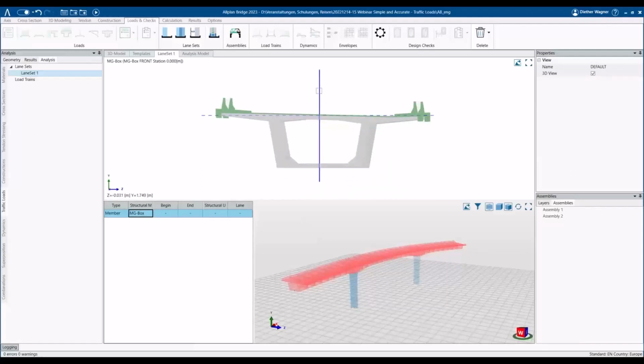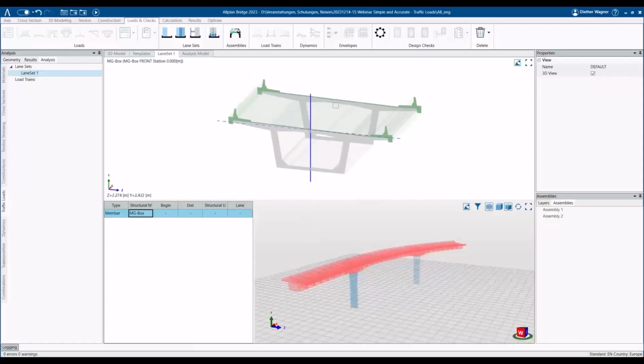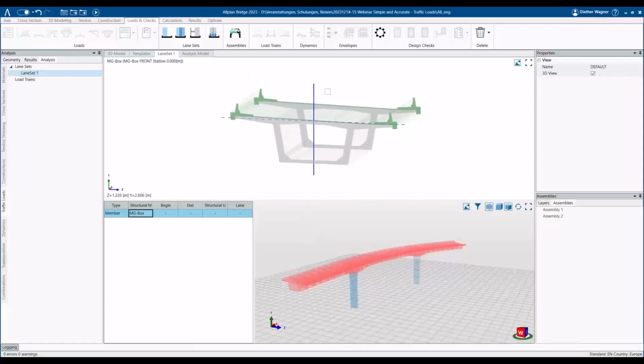So if I now would start to define a lane, it would refer to that line. We can also shift this afterwards. You will also see this in a minute when we then copy it. But I will do it right now at the beginning. So I want to move this line. If I click the line, I have here in the context menu the offset, or you just click this tool here. It's exactly the same. To put this basic reference line to the right position. And now I can move it here interactively.